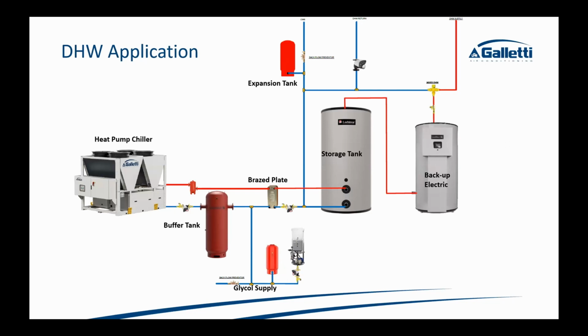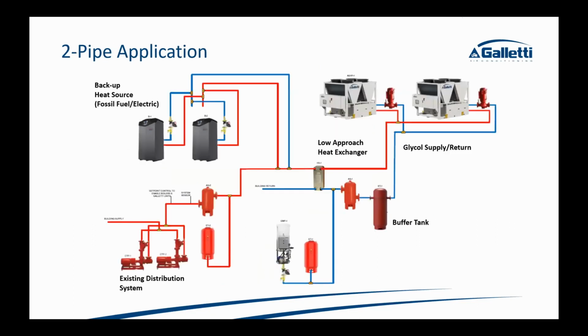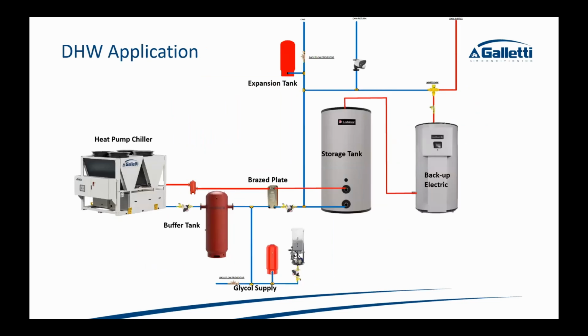exchanger isolating these circuits, just like the last one. Now, if the entire system was glycoled, that wouldn't be necessary. So I just added that, assuming that we're not glycoling the entire system. Many of these manufacturers won't require that you glycol the outdoor circuit, and they'll have different ways of having pipes wrapped or preheated, but that doesn't seem to make a lot of sense.